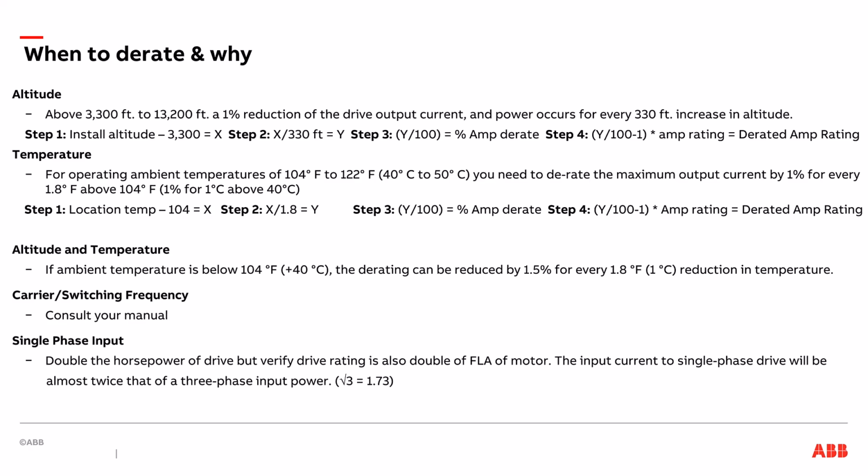This results in an input current for the drive being much higher. A single-phase input delivers 1.73 times the current of a 3-phase input. In other words, it's almost twice as high. This means the diode bridge will be seeing higher currents than it was originally designed for, and you'll see the DC bus having a higher ripple current, creating extra heating for the bus capacitors. In this situation, you will typically double the size of the VFD you select.